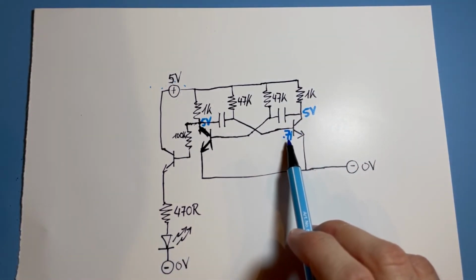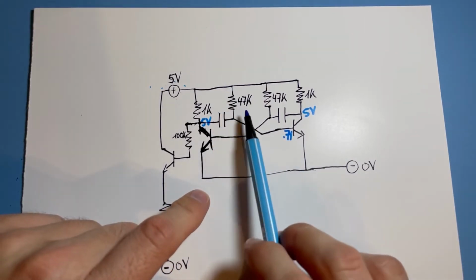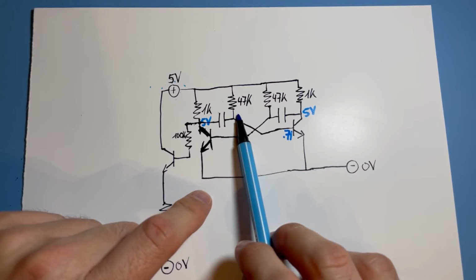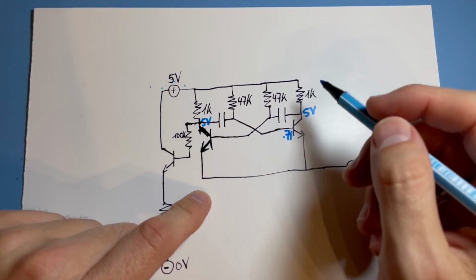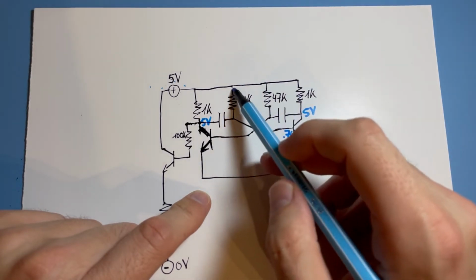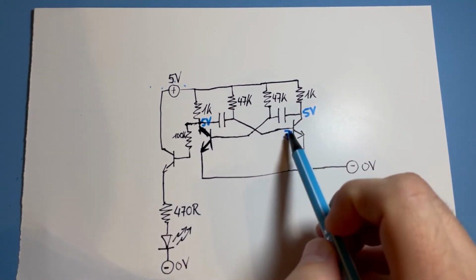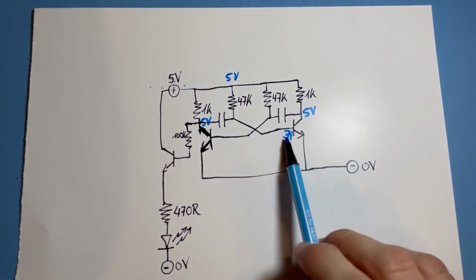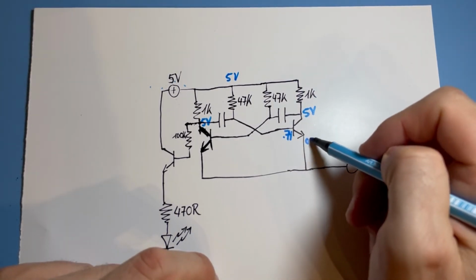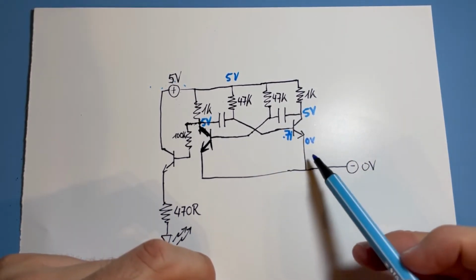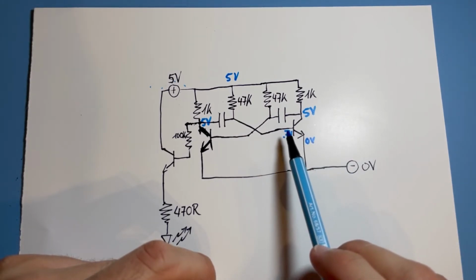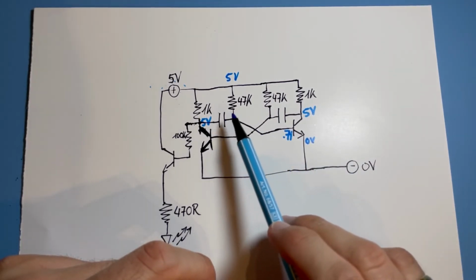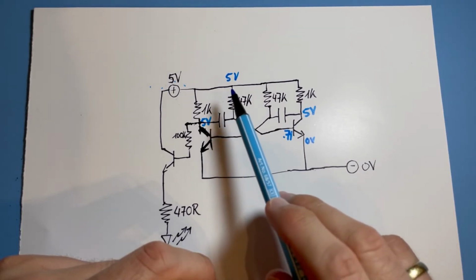And here will be 5 volt, and there will be everywhere 0.7 volt, and up here there are 5 volt, of course, everywhere. And once we get here, of course, we have 0 volt, because that's all connected to ground. So just before the transistor at the base, we have 0.7 volt, all in here, and here we have 5 volt.